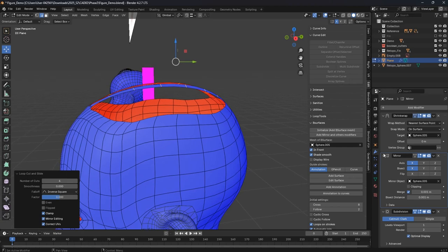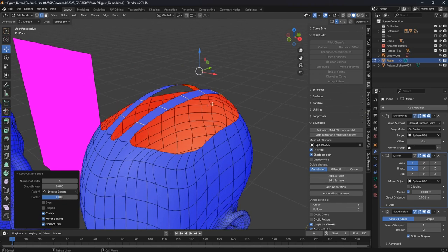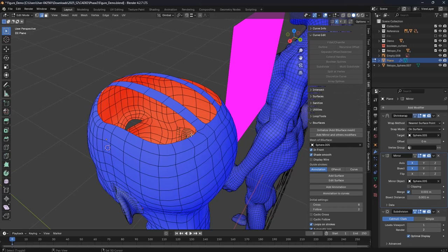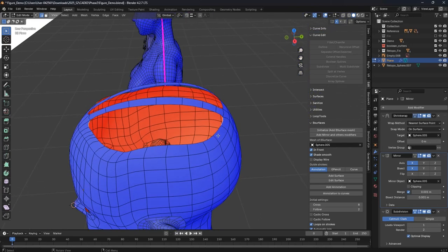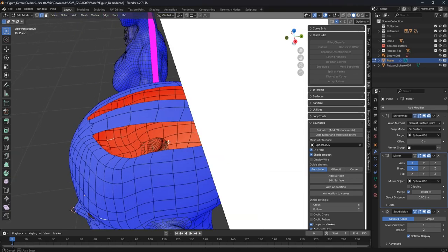Since now we already have applied the shrinkwrap modifier, the result will be automatically snapped to the original reference shape, which means our sculpting model. So that's the idea. Let's quickly finish this part, and then we can merge the separated vertices together. Press F key to merge them together, Ctrl and R, and increase the number of the segments and turn that one to 6. So let's quickly finish that one.